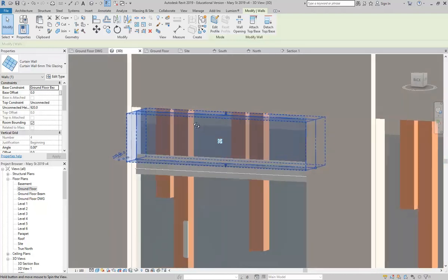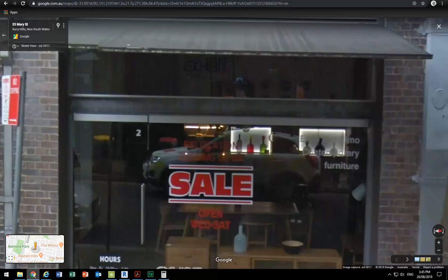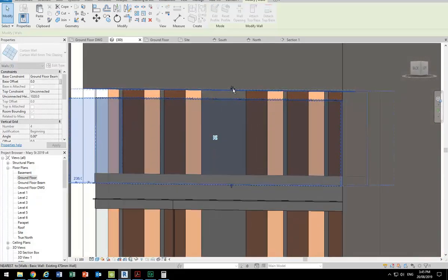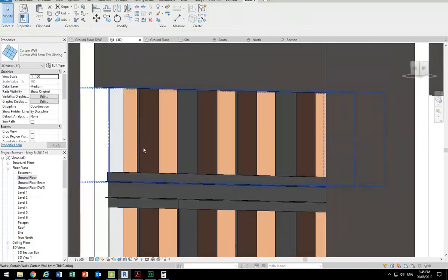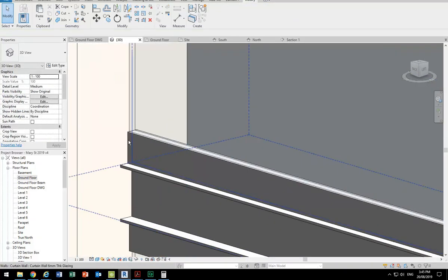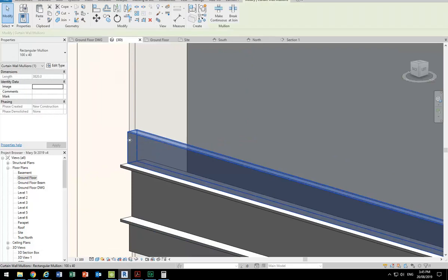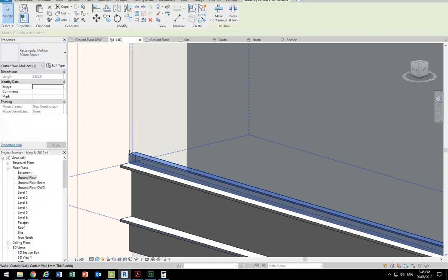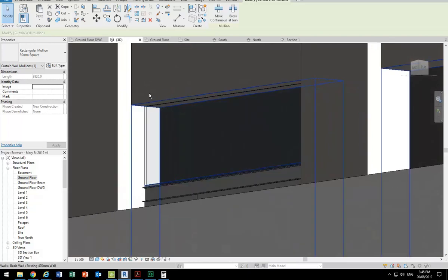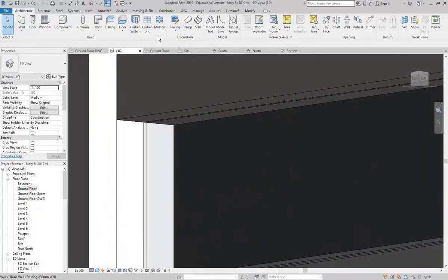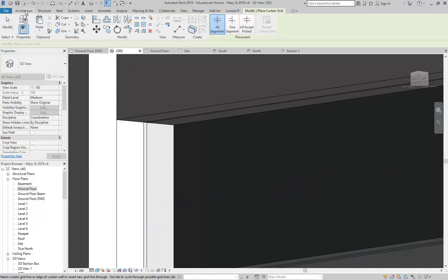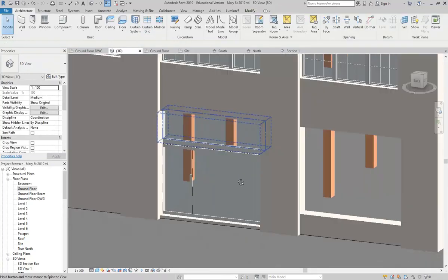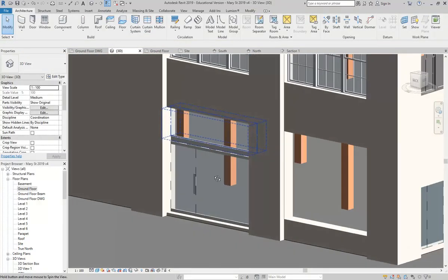Okay, so if you want to, you can put the mullions on the same. There's this one. Actually, that one's just the thinner one, so I'll just stretch this up. So I'll just show you one last mullion. There you can see it's got this mullion that I made, but I want the smaller one. So in your default list of mullions, you'll see there's this one, 30mm square, which is a nice plainer one you can use for smaller ones. And I'll just put another one on top. Oops, sorry, not a grid, mullion. Anyhow, I could go a lot further, but it's probably good just to maybe see if you can get to that point.